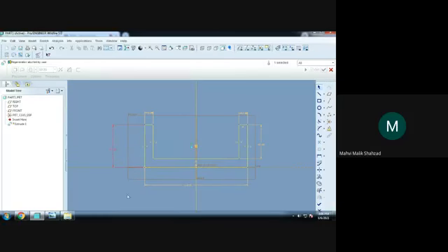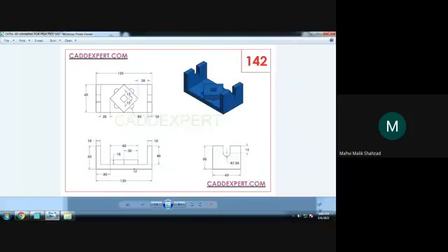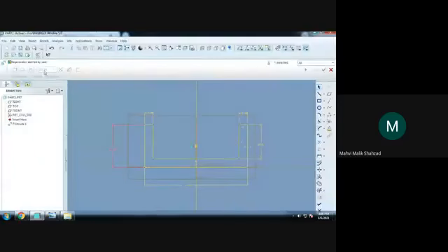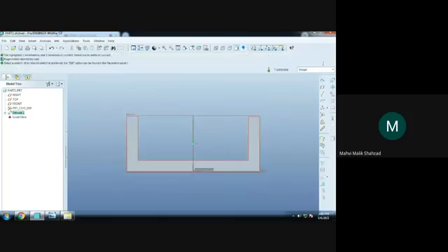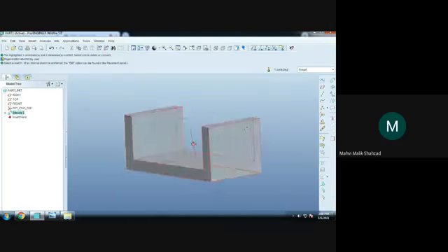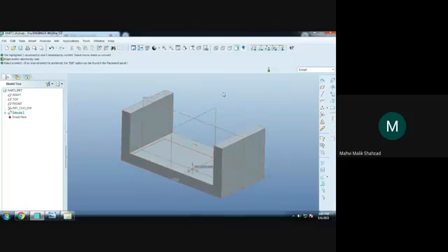Okay. Now it's clear now. Just go through the drawing. This dimension is 120, then 40, 10, 10, again 50. So I will extrude this section up to a 60. Okay. I have given here 60 symmetric about the plane. I will click OK, then preview, then just see I have got this C section.